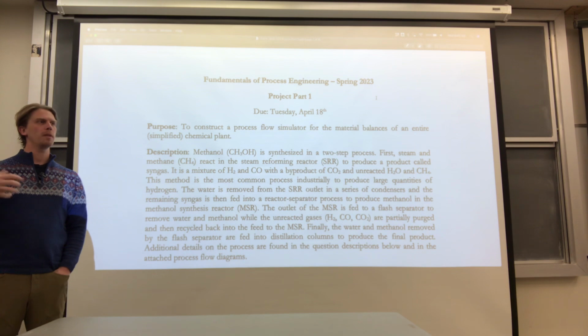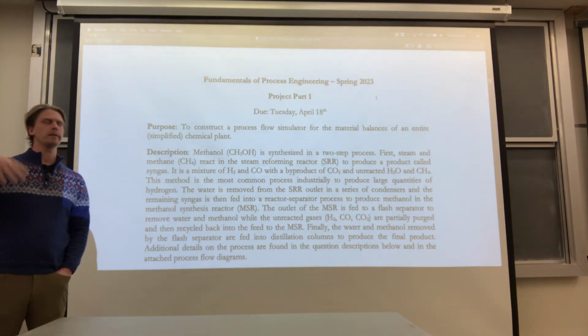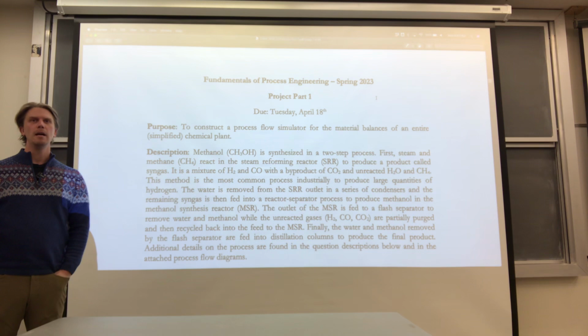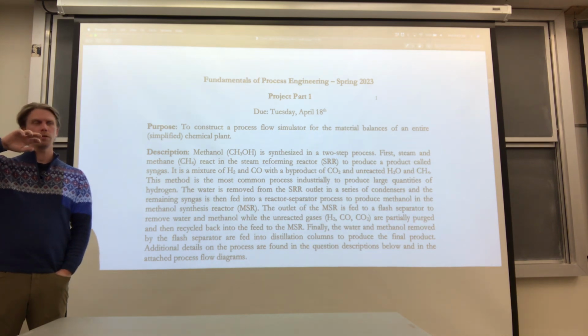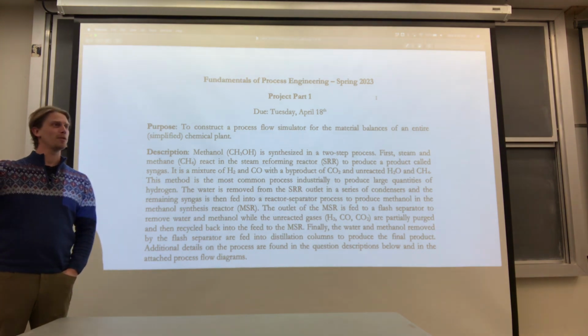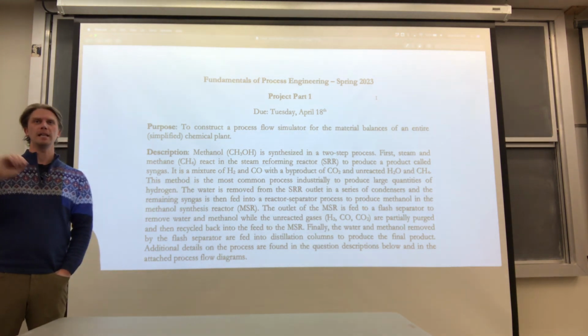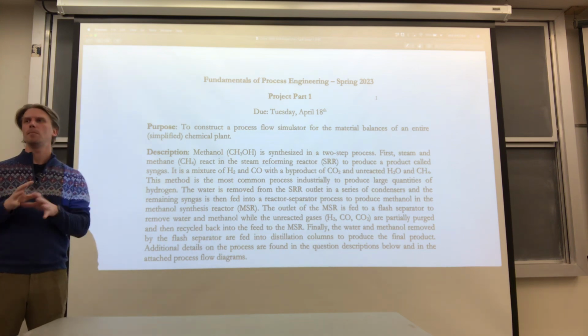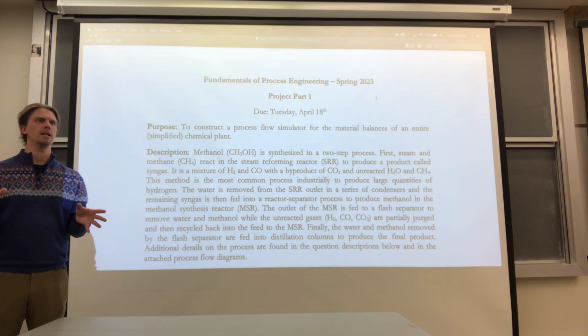But I really hope that after a couple more examples, it can click and you're like, oh, okay, if I just set up the data tables, get all the heat capacity information, get all the heat of formation method, right? The difficulty of translating the word problem of a process is mostly in getting the process flow diagram drawn out and the material balances. Once you have all the material balances, the energy balances should almost be identical for almost any process that we do, right? It's just a matter of finding the right enthalpy values.